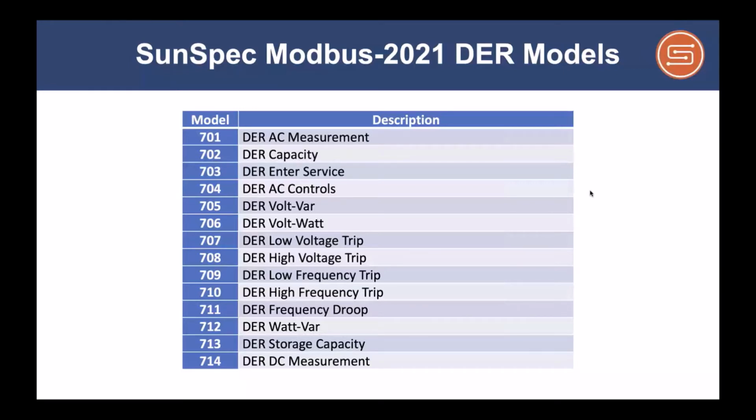Another important aspect of this capability, this technology, if you're a longtime SunSpec implementer, is that this functionality supersedes the 100 series inverter models. According to how SunSpec works, we always support interfaces that we publish, and once a product is certified, that means it's forever, but the certification is tied to a set of models. So these models are the recommended ones if you're developing inverter-based products. You can certainly use the others, but if you want to sell in the territories that require IEEE 1547, this is definitely the preferred method and the path of least resistance, and of course, also the path of greatest capability, is to utilize all of these models.